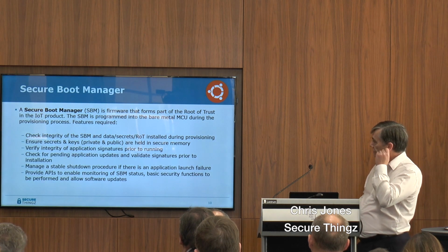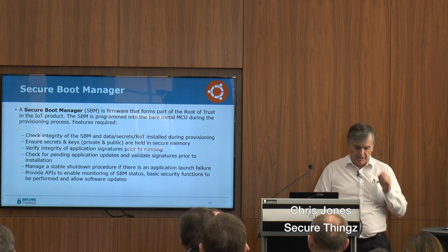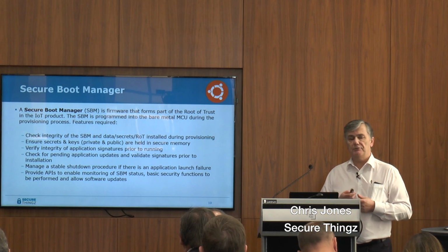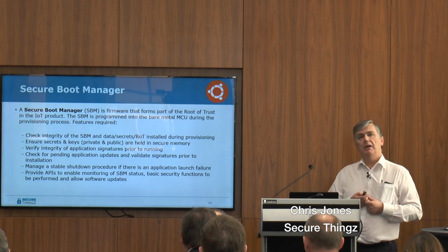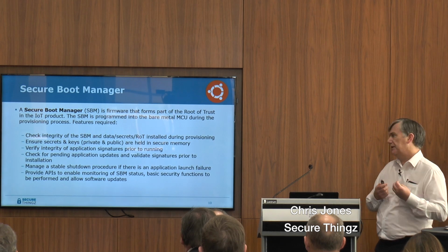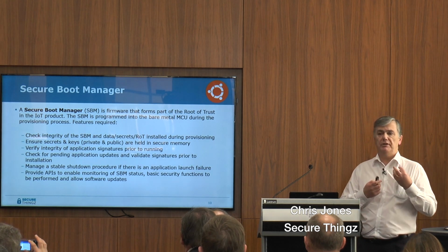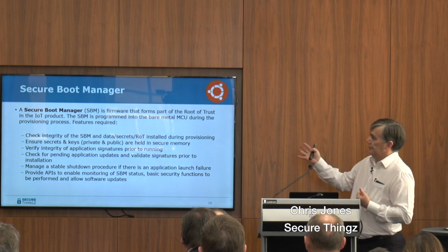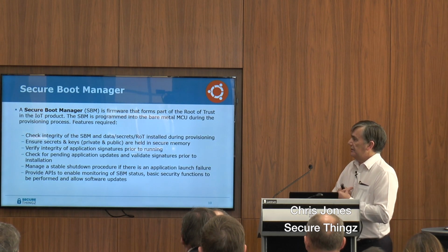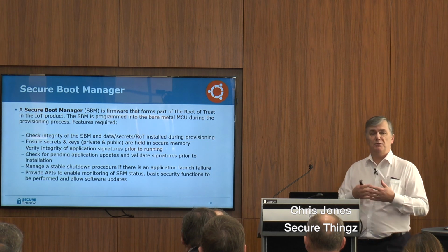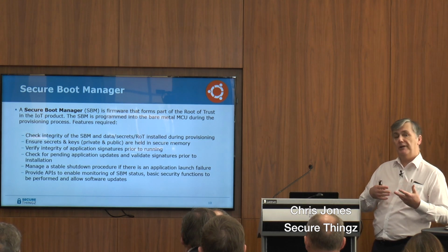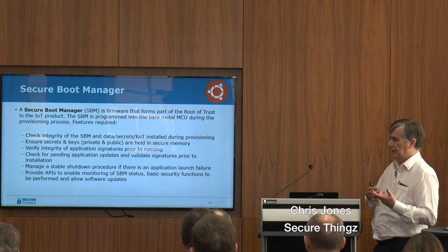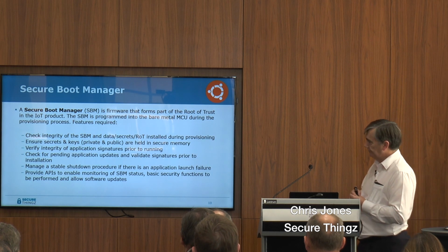So, as I said, a secure boot manager is a little bit more of a sophisticated kind of entity, a bit of software that's running in the device. It generally can handle all the security things you need, like using the keys. So one of the things it can do is check the integrity of itself. It's kind of ideal to make sure before you boot up that you're real and you haven't been tampered with. That's often a first check. It does a quick integrity check of itself.